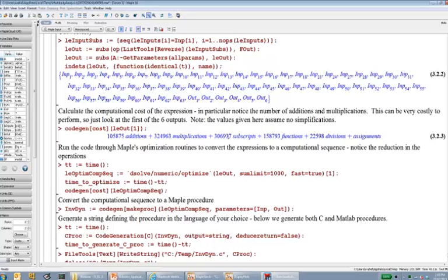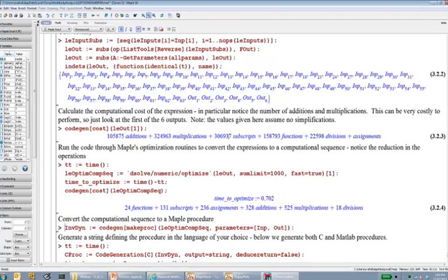But we can use Maple technology to optimize this huge set of calculations symbolically. What is meant by that is, when you have a big set of equations, there are a lot of trivial calculations that, if you are not doing the optimization symbolically, you need to pay the price for at each step. There are repeated expressions that you will calculate over and over again. If you can in some way detect and isolate them, then you will only calculate them once. There are different levels to this optimization, and this is the result of that optimization.